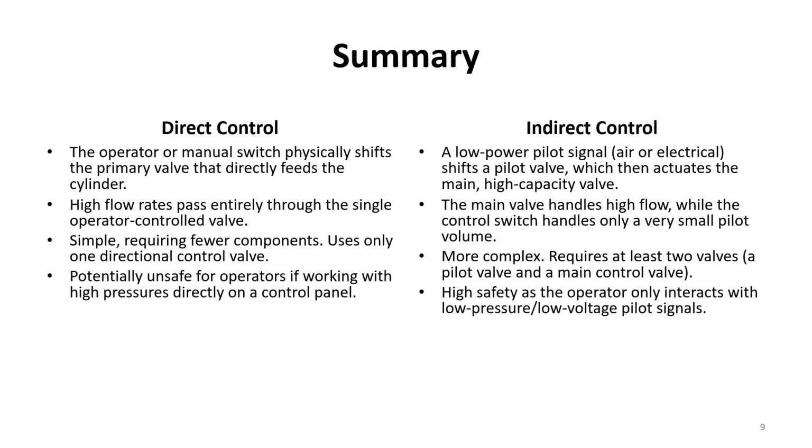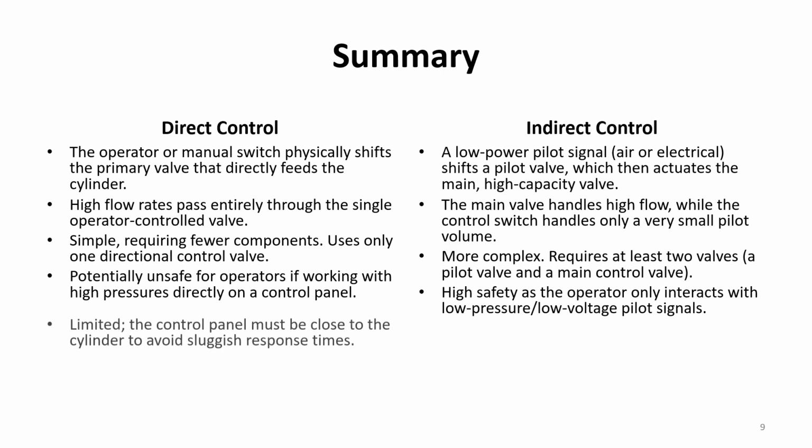Whereas in indirect control, it is much safer, as the operator who is manually controlling the DCV is only handling a low pressure or low voltage system, which sends the pilot signal to the high flow rate and high pressure handling DCVs.